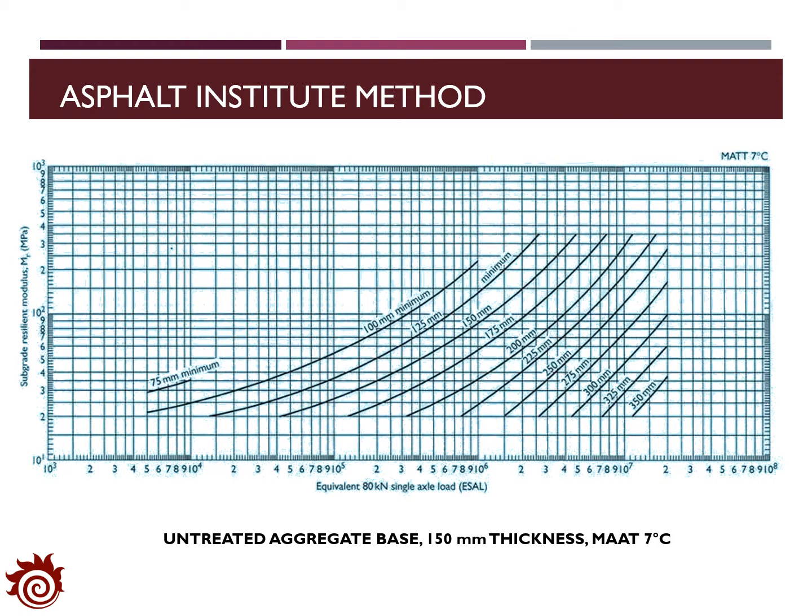In this page, we have one chart to show the estimation about the thickness of the pavement structure for the deep strength pavement. Basically, for the deep strength pavement, we have the asphalt concrete surface, the asphalt concrete base, and the granule base. And behind the granule base is a subgrade. The chart will provide the thickness of the asphalt layers, including the surface and the base layers.